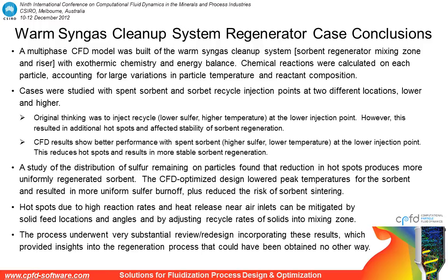The CFD results pointed to more likely better performance with the spent sorbent, which has higher sulfur and lower temperature, at the lower injection point. This reduced hotspots and resulted in a more stable sorbent regeneration. I should point out that this process is still being developed, but it underwent very substantial review and redesign after the results of the CFD.